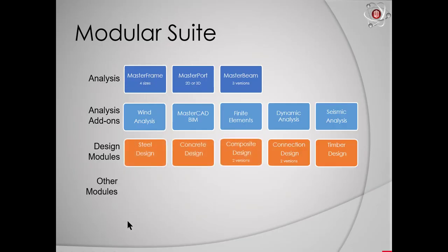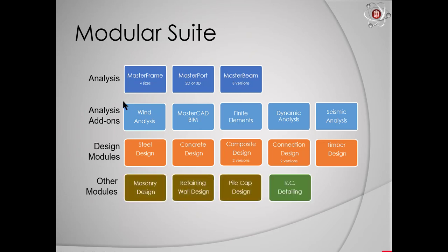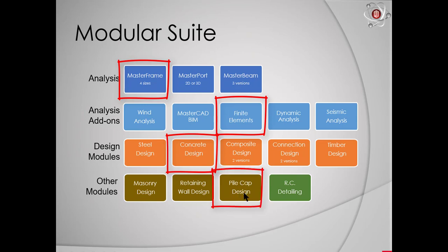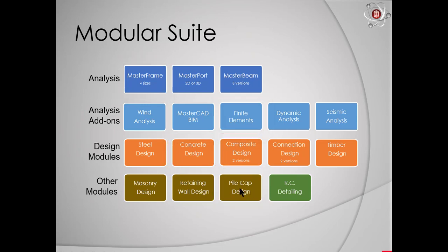The MasterSeries is a modular suite. What we'll be looking at is the frame analysis. We'll be looking at the frames. We will be looking at finite elements for doing our rafts. We will also be looking at concrete design for doing our ground beams, and we'll be looking at the pile cap designer.